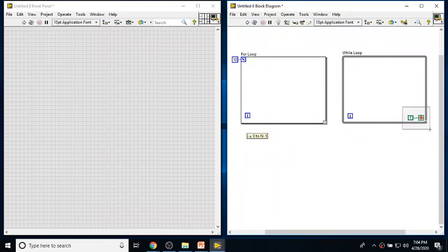So what happens is when the constant starts executing, it can never be changed. During the execution of your program, you can never change this constant value. You can never convert this to be a true like this. Now I'm converting it because it's in edit mode, not run mode. So it cannot change from false to true, and the condition will never be satisfied. True means the condition is satisfied and false means the condition is not satisfied, right?